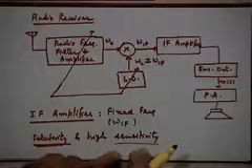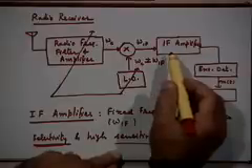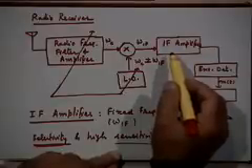Let me tell you something. We said that this has to be highly sensitive, which means the gain of this amplifier should be large. Can that create problems? Suppose the signal that is coming in is already very strong and you have a very large gain sitting here. What can that do to the system? The amplifier will go into saturation, right? So we don't want that situation also.